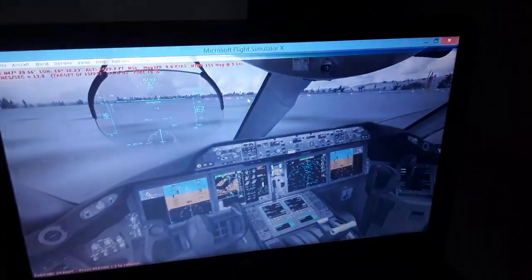So we have the onboard antennas of the aircraft that receive the LSZH localizer, the instrument landing system of the airport. It displays the horizontal localizer and the vertical glide slope, and we can tune either manually or automatically when we select the runway for takeoff or for landing from the flight management computer. We have also the localizer crossbars. We have the flight director crossbars for manual guidance of the aircraft, and the autopilot crossbars for automatic guidance of the aircraft. We have the angle of attack of the aircraft as it flies in flight mode with the autopilot and the auto throttle.